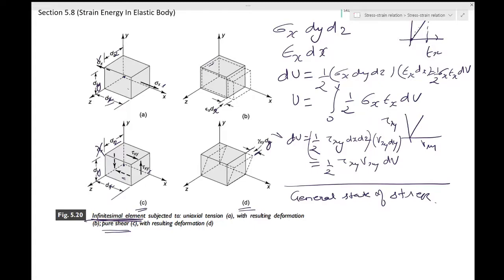That is an assumption we always take. So if we imagine a gradual loading process in which all stress components maintain the same relative magnitudes as in the final stress state, the strain components will also grow in proportion, maintaining the same relative magnitudes as in the final strain state. The whole point is that all of them will deform individually.